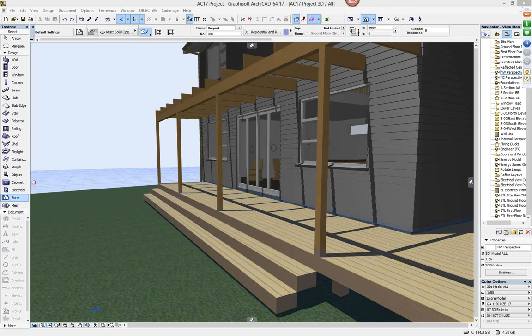Now, there's a lot of keys that I quite like. It's more than just explore. You can get some pretty good information about this. One of them is I for information. So if I hit I, you'll see a little crosshairs appears in the middle of the screen. The idea is if I hover over anything, you see a white box appears around it, and if I click, it tells me the information about that particular building element. This is BIM. So I can see the column size, its profile, what layer it's on, etc. So if you're using this on a...